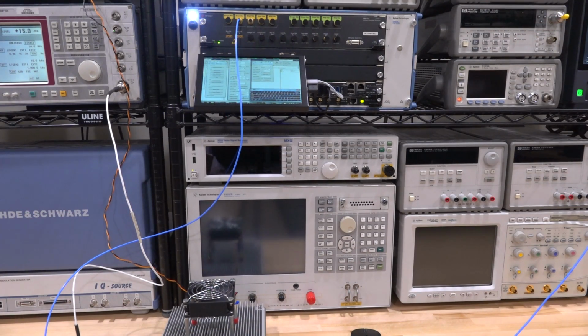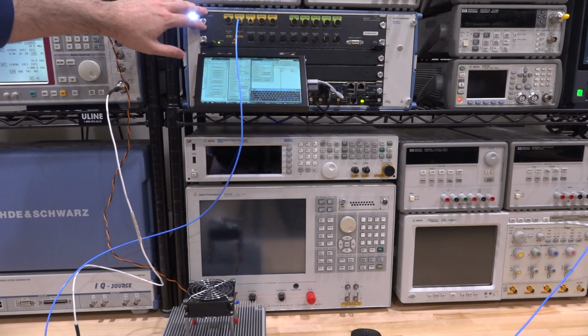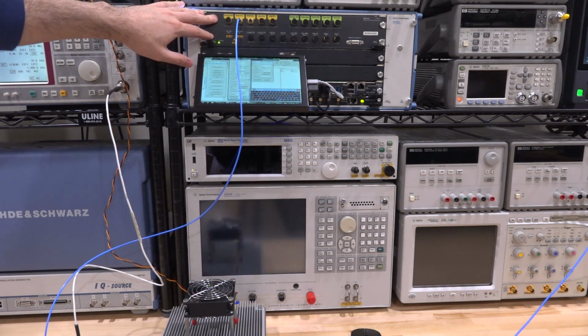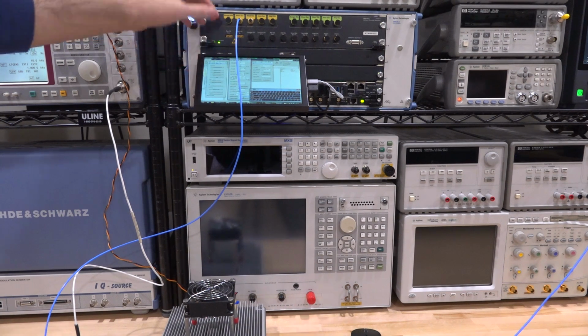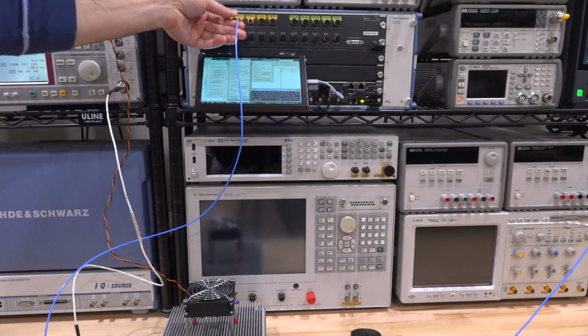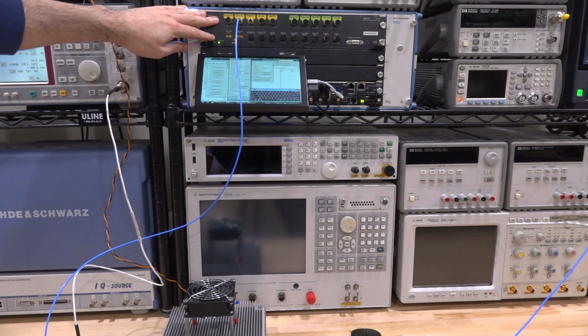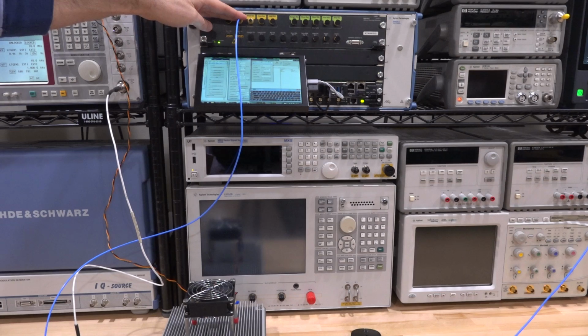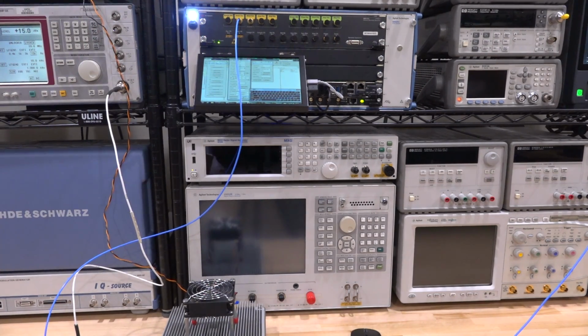So let's now continue our analysis, but now we're going to use the Keysight M8190A to generate our IF source. This instrument does have digital up conversion capability, so we can actually create an IF carrier up to a few gigahertz, and then we can put any modulation we want on top of that with a wider bandwidth. So I'm using 3 gigahertz again, 64 QAM, but this time at 250 megasymbols per second.